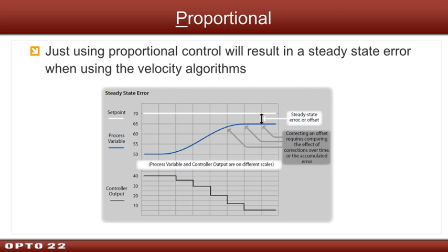But ultimately, once the process variable starts to level out and the error gets less and less, the output of our controller is going to be less and less until ultimately they both steady state. The problem is that this error between the two could be quite high, and we're not going to know what the error is because when you subtract the set point and the process variable, it's going to be 0, and the 0 error is what results in the 0 change.